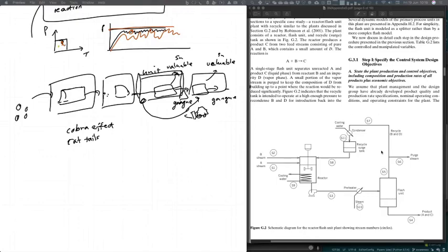So actually on this higher level, you realize that to a certain extent, it doesn't really matter whether the PID controller is tuned properly. The main challenge of a control engineer in practice is often just to stop people from putting the controller in manual. Something like 2/3 of controllers have been found to actually make control worse. And largely that is because they're being used incorrectly. Part of it is because they're being tuned incorrectly, but also part of it is just that people turn them off and prefer to just control the plant manually. So it's a really tough question.